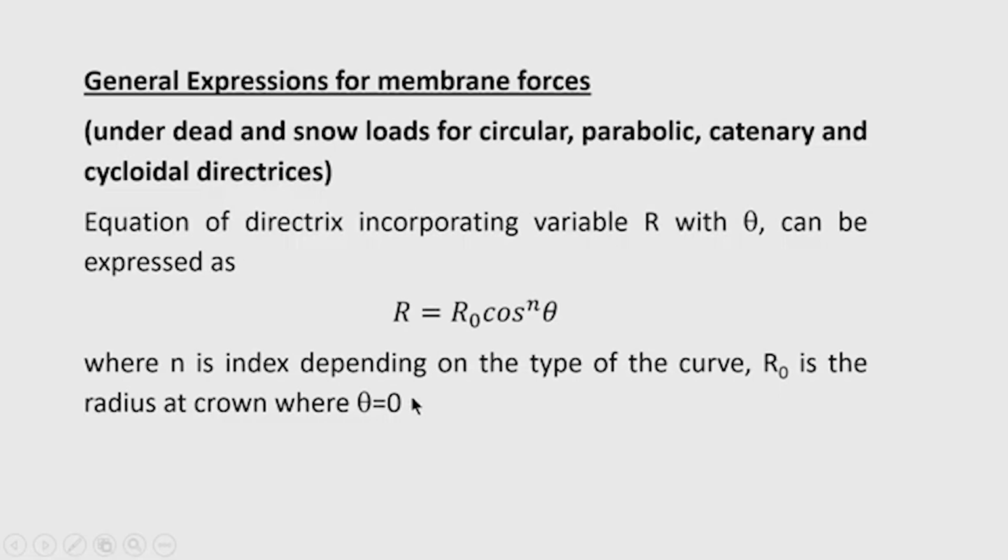Now we have obtained a general expression for the membrane forces for the gravity load as well as snow load. Gravity load here I mean self weight plus live load, and snow load is also a gravity load, but it is acting over the horizontally projected surface.